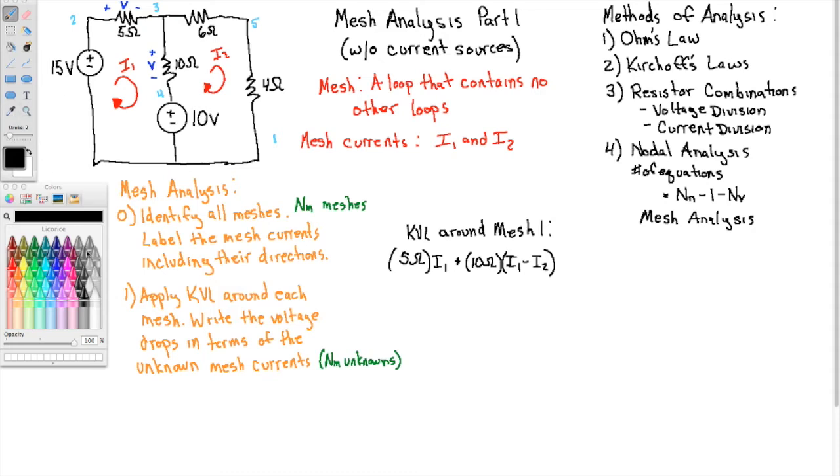Okay, well remember I'm adding the voltage drops. So now I want to know how much does this drop by? Well, by definition of a voltage source, that drops by 10 volts. So plus 10 volts. Right, it drops by 10. Notice the polarity of the battery. It drops by 10. So now I'm here at node 1, down here.